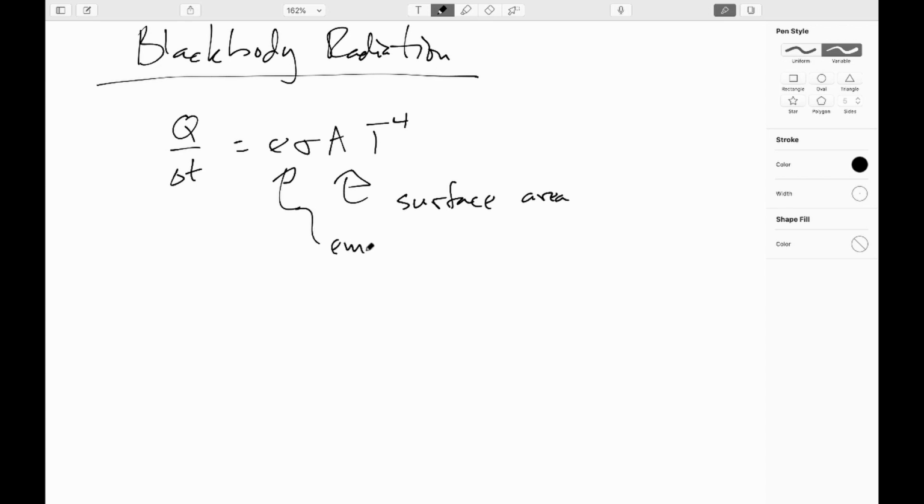It's called the emissivity. It's the radiation efficiency. And this is just plain a number that will run between 0 and 1. If the number is 0, you are a perfect reflector. You can't absorb any heat. It also turns out you can't emit any either, so that doesn't happen in practice. And 1 is a perfect absorber, which will both do a perfect job of absorbing heat and also a perfect job of emitting heat.